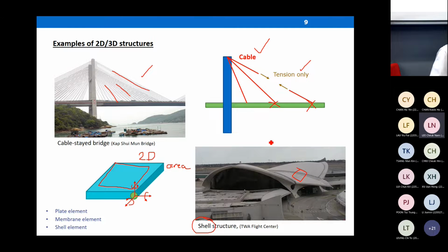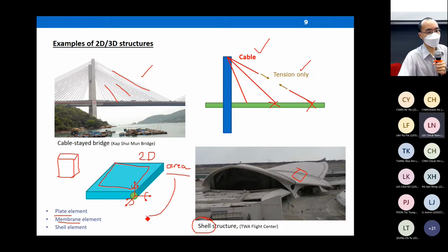Or if you want to model a shear wall, which is also a plate oriented vertically, right? If you want to model a wall, then you also need to use this kind of area element. Normally, you use area element, not always, but normally. You can use other methods to do the modeling. Computer modeling is quite special; we have many modeling skills. For area elements, there are 3 types in general: plate, membrane, and shell. We will discuss more during the workshop, the SAP2000 workshop. In our lectures, we will not put too much time on area elements. We mainly focus on 1D elements.